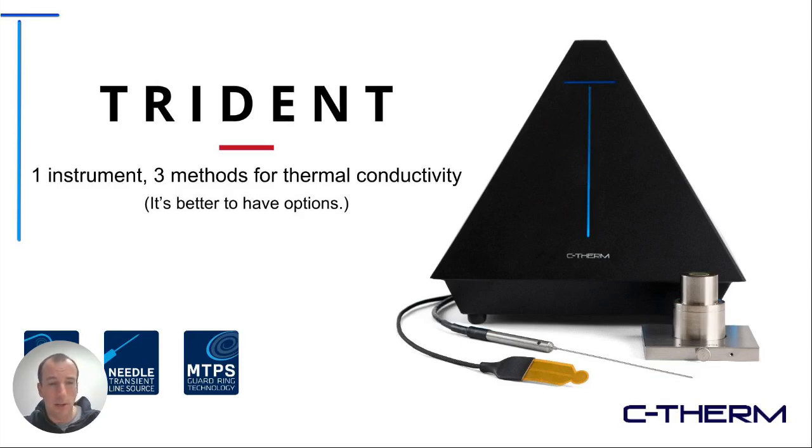The Flex transient plane source, that TPS method, is more complicated to run, so it requires a better trained, more experienced operator or user, but it gives you a lot more control over the experimental parameters in running the measurement. So in adjusting test time, the power to the sensor, there are different size sensors available for the Flex TPS. So it's all about flexibility, the Flex TPS sensors.